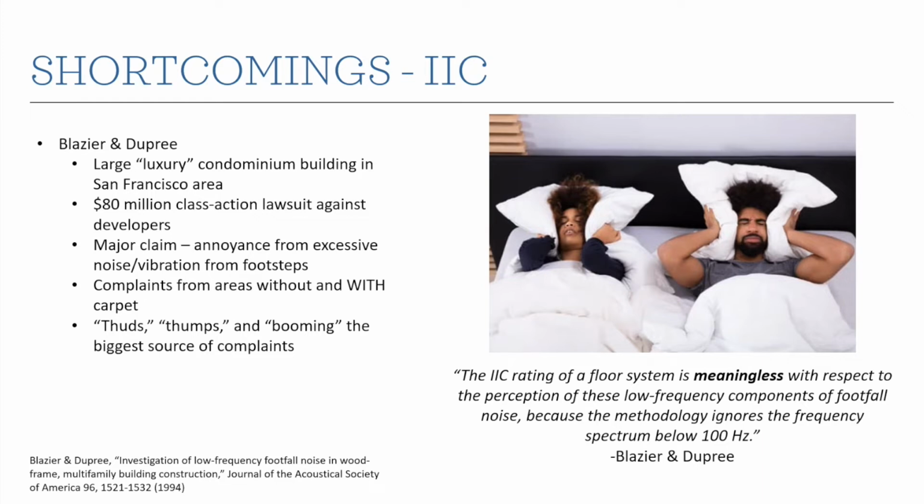So when we talk about limitations of the STC rating, it's designed around speech, so it's got this limited frequency range, but we don't really produce a bunch of sound outside that range when we're speaking. But for footsteps, the IIC rating ends at 100 hertz, but our footsteps might very well produce significant noise below 100 hertz, and that's ignored by the IIC rating.